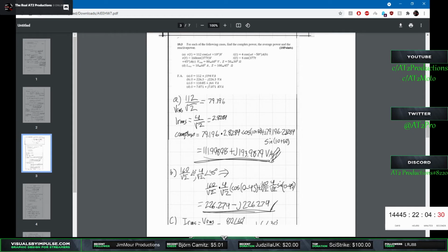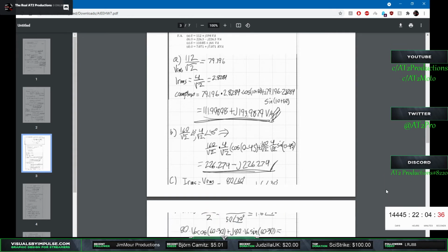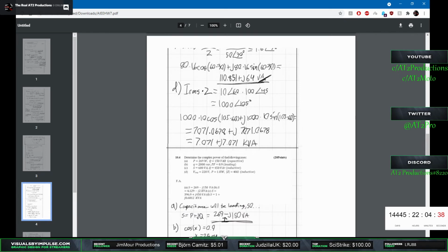Okay, I'm still a little weak on this. Give me a little more info. Okay, so this system is a motor control system. It's actually the VFD, the variable frequency drive, that runs the motor. It acts similar to a dual conversion battery backup system. You're taking line AC in, converting it all to DC, then off that DC bus, firing your SCRs to give a controlled AC output at the voltage and frequency that you want.